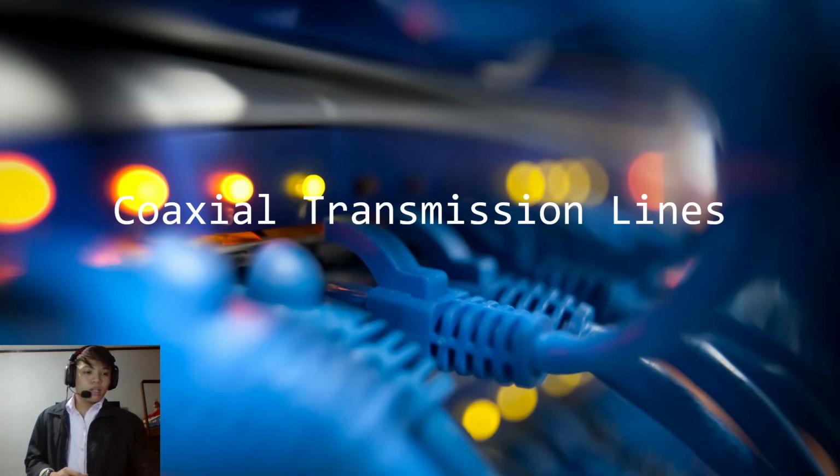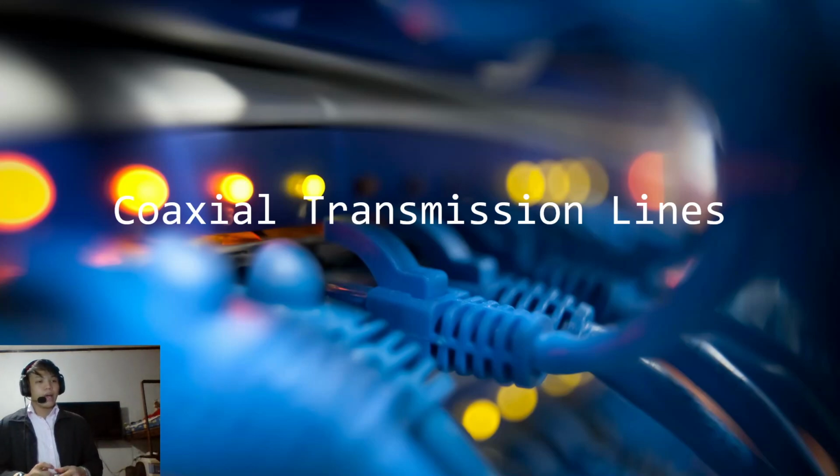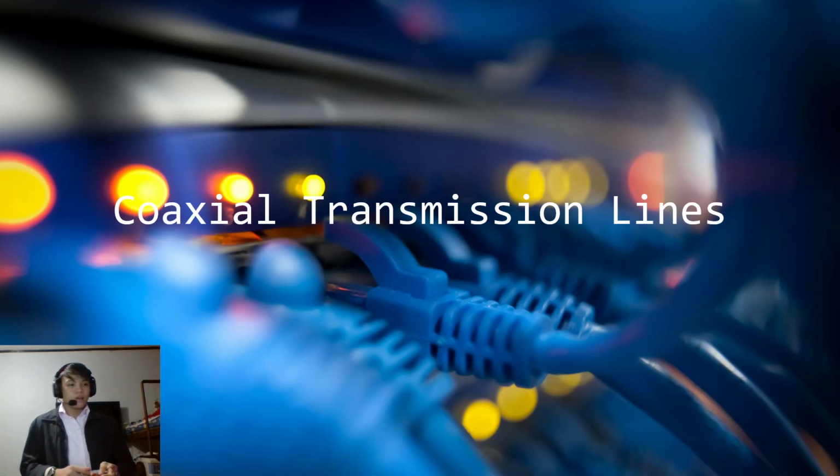The next one is the single-ended or unbalanced line, where one conductor is grounded. The rigid coaxial line contains two concentric conductors insulated from each other by spacers. Some rigid coaxial lines are pressurized with an inert gas to prevent moisture from entering.